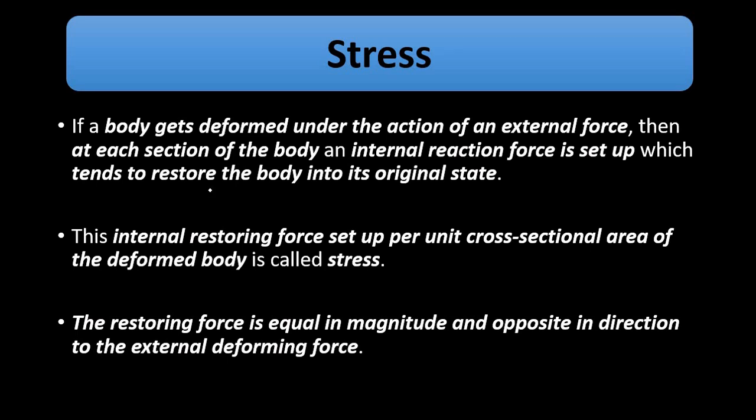So this internal restoring force or reaction force which is acting per unit cross sectional area is called stress. As the restoring or reaction force is equal in magnitude and opposite in direction, it is equal in magnitude to the external deforming force. That's why if we write it as deforming force by area or reaction force by area, it is the same thing.